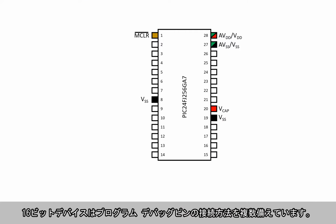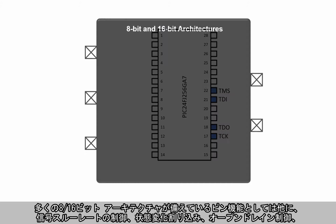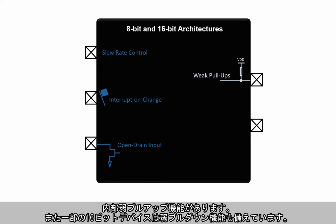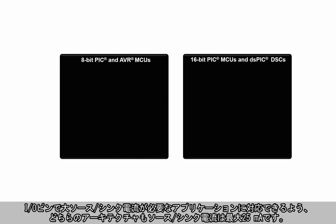16-bit devices also feature the flexibility to choose from a few program debug pin connection options while also adding the ability to simplify production programming diagnostics by providing a JTAG boundary scan option. Additional pin capabilities on many 8 and 16-bit architectures include the ability to apply pin signal slew rate control, interrupt on change, an open drain control option, and the ability to apply on-chip weak pull-ups with 16-bit products also featuring weak pull-down options on select devices. In applications where high current sourcing or sinking is required on I/O pins, both architectures boast 25 mA source sink capabilities.